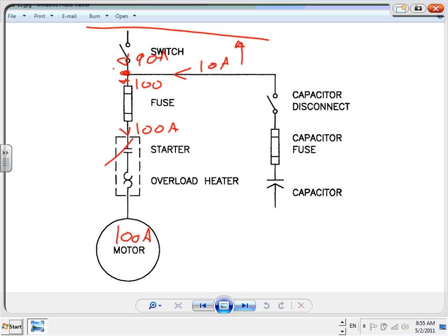So how do you solve this problem, DJ? You come over here and you put a contactor, starter. Right? So I put a starter and I interface. See these two starters? You have a control circuit that when you push the button and you start this motor, guess what? At the same time, you turn this capacitor on with the starter.